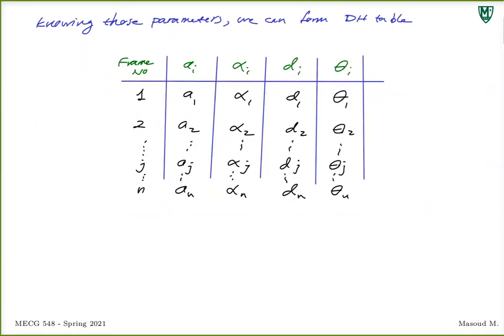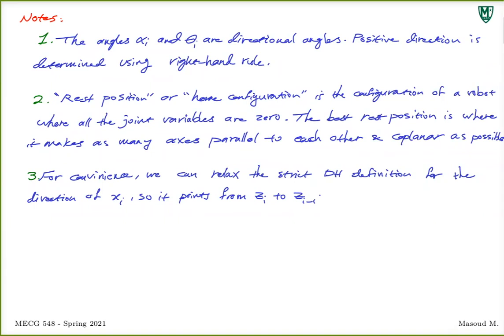So like this DH table we form here, we want to make these parameters 0 whenever we can, as long as we're following the rules. This flipping of the direction is something you will see happen, and you're allowed to do it as long as you can make more parameters 0. More 0s, the better, generally speaking. It makes our lives easier.